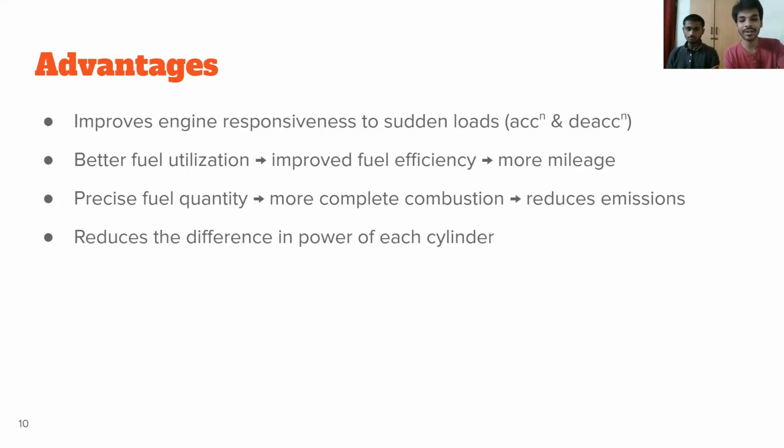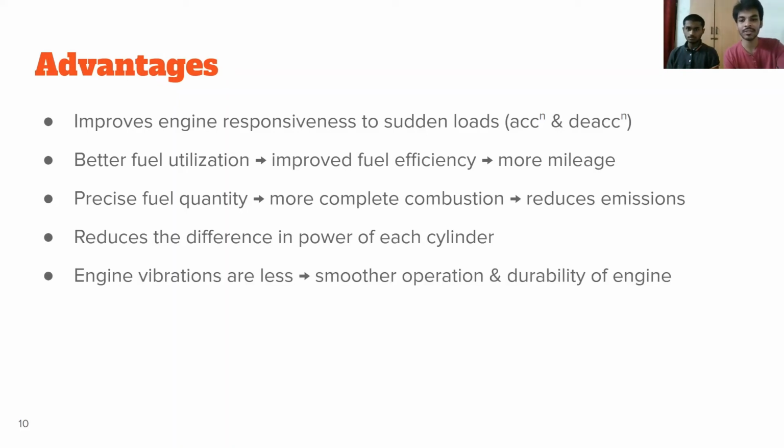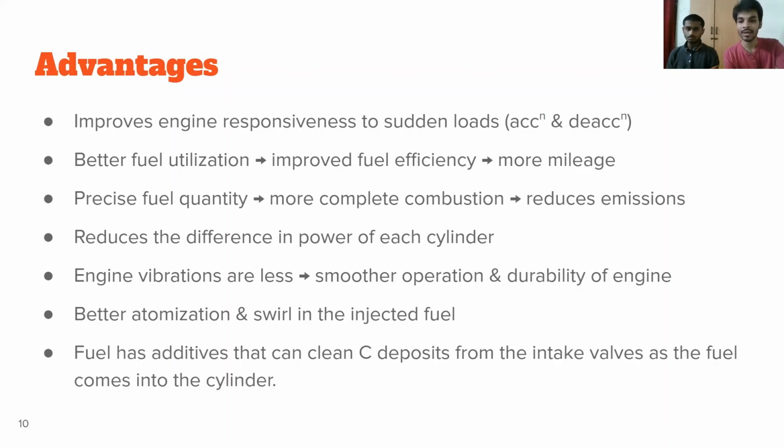And the difference in power in every cylinder is also reduced because we have control over each and every fuel injector of each cylinder. The engine vibrations are also less because, due to complete combustion, smoother operation can be present. The fuel injection allows for better atomization and swirl in the injected fuel, hence proper mixing is also present. Different additives can be added to the fuel such that carbon deposits do not form in the